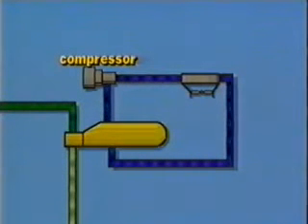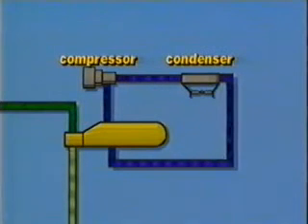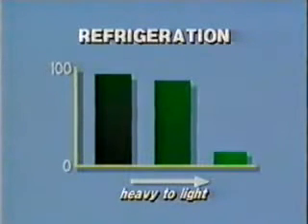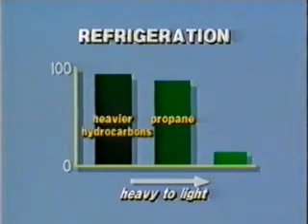Compressing the refrigerant and driving the condenser are the major energy requirements of refrigeration. Compared with lean oil absorption, refrigeration uses less equipment and energy to recover similar amounts of heavier hydrocarbons. Refrigeration separates about the same volume of propane and heavier hydrocarbons as lean oil absorption does. In addition, it can recover small amounts of ethane.